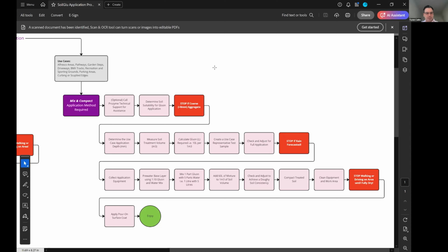And this is trial and tested. This is actually used extensively in the mining industry. They do this on haul pack roads. They're 80-ton machines with hundreds of tons worth of stuff in the back, and it's still effective on those roads. The other advantage is that it tightens up the surface of the road and makes it a bit stronger, so it's less prone to potholing and other issues like that. So you can extend your maintenance intervals on those types of roads.